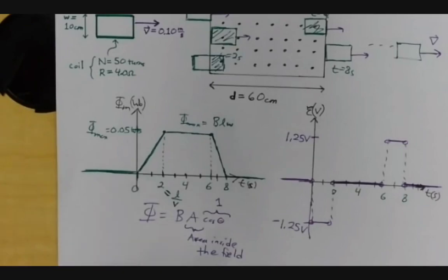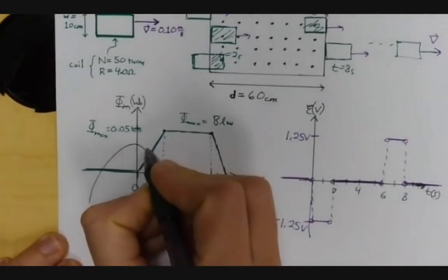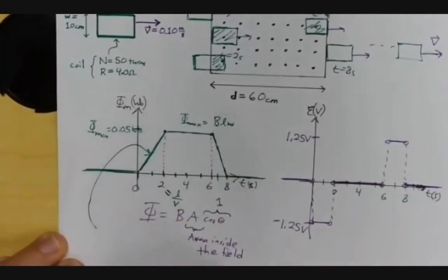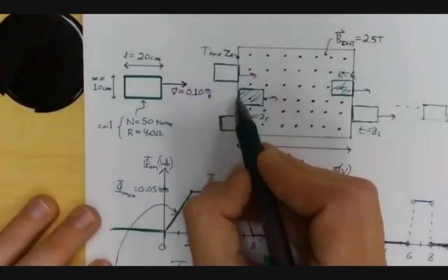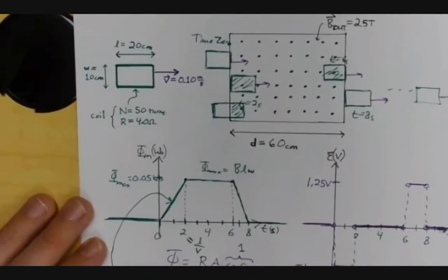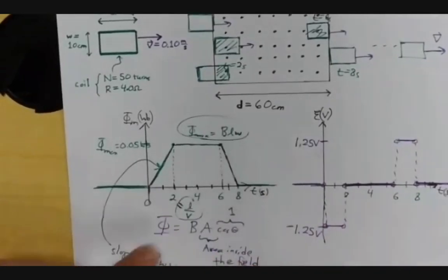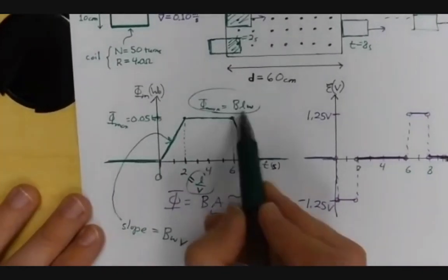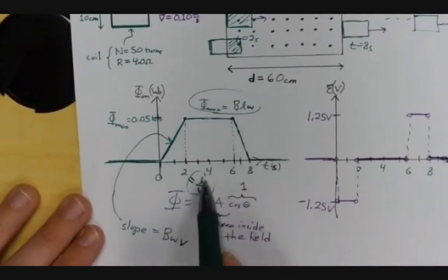Let's just say what these would be here. What is that equation right there? Or what is that slope? The slope is proportional to the magnetic field. It's proportional to this dimension of the loop W, and it's V. You can see it here. It's this divided by this. BLW, that's the rise, BLW minus 0, over run, which is L over V minus 0.